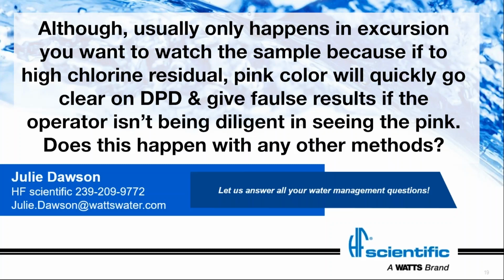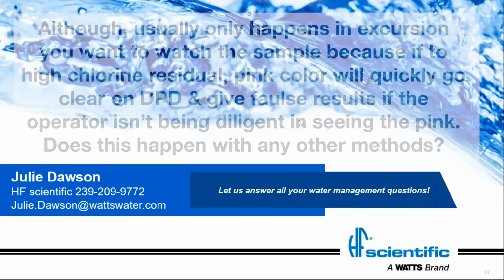Or you can dilute your sample, but we want to be careful when we're diluting our sample that we're diluting it with DI water and that we're not creating bubbles and not stripping out chlorine and all of those issues that come with it. So if it's a routine sample that's above 10, I would say you'd want to look at the ion selective electrode method.